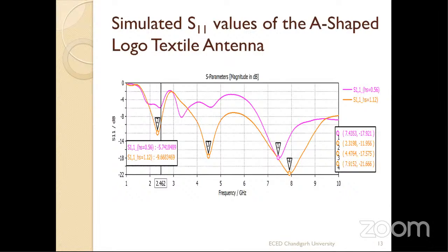If I design the antenna, this A-shaped antenna will work well in the ISM band and it is applicable for other wireless frequency bands also. But our requirement is always that the antenna should be thin. If we are using a 2-layer antenna, some air gap will be there and there will be more losses. Practically, it will go like that. So the main consideration is that we should use the minimum thickness we can go for, for our designing.